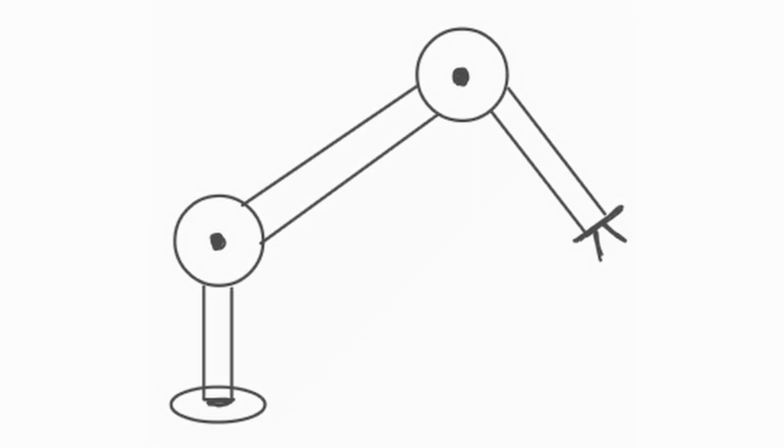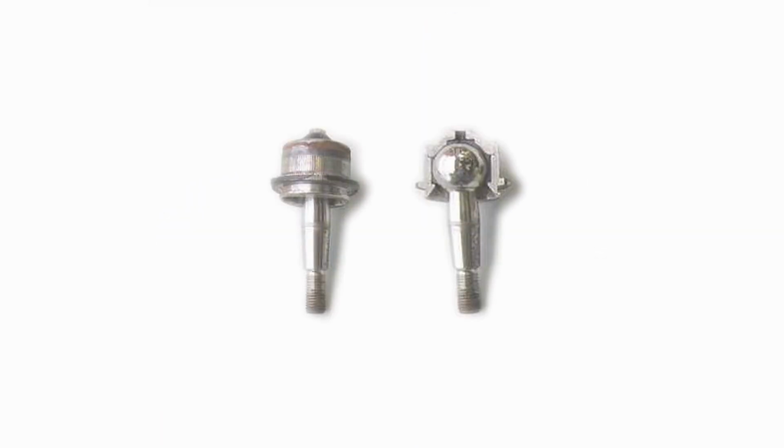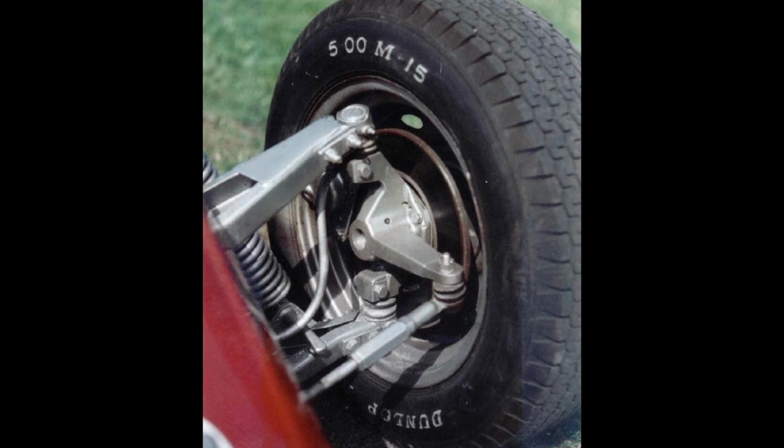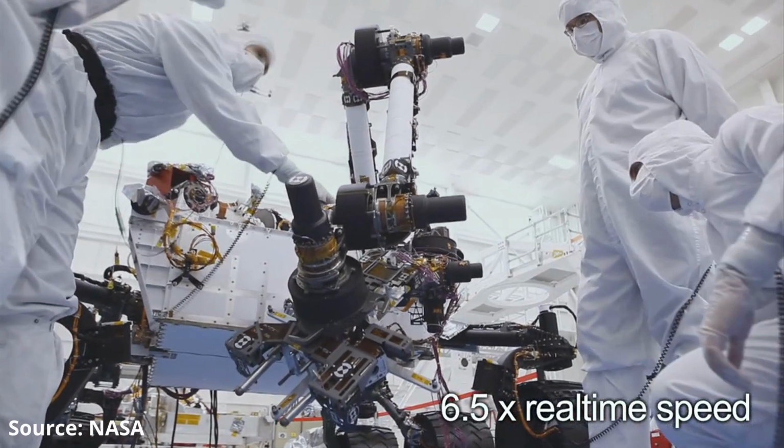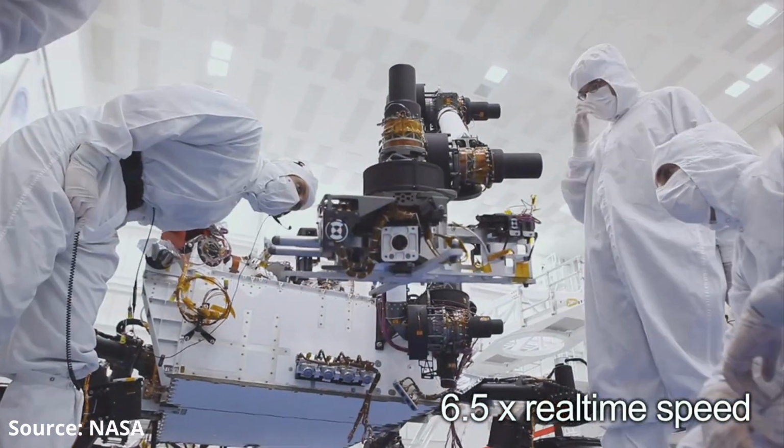When combined in a robotic arm, each joint adds its respective degrees of freedom to the chain. In this way, it is also possible to create and thus replace a spherical joint by combining 3 revolute joints. Spherical joints are very difficult to implement as active joints. In fact, they are often used as passive joints. One example for this is the usage in car suspensions. Modern rovers use mostly revolute joints with electric motors because they are relatively simple to implement compared to other types.